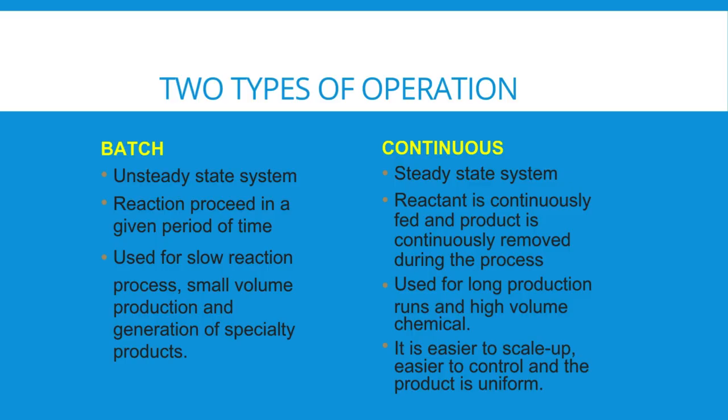For batch reactor, the process occurs in an unsteady state system. The reaction proceeds in a given period of time. Batch reactor is suitable for slow reaction process, small volume production and generation of specialty products.